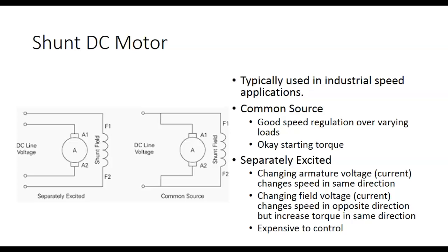So we had some motors out at US Steel, compound motors, and we literally controlled both of them. So if they wanted to increase the torque and leave the speed alone, they would increase the field and increase the voltage on the motor to cause it to run the same speed. It was a really cool system.